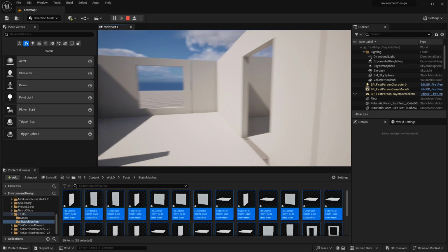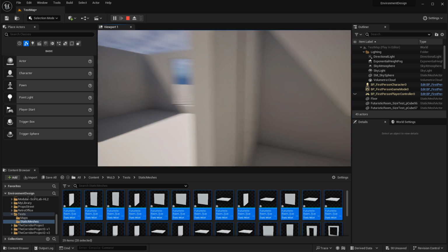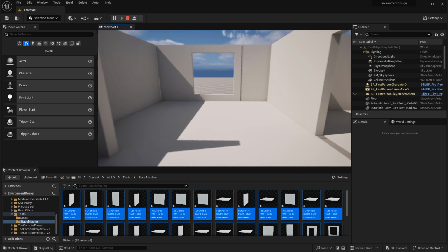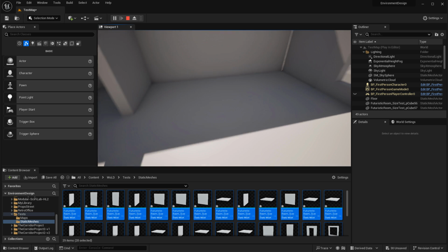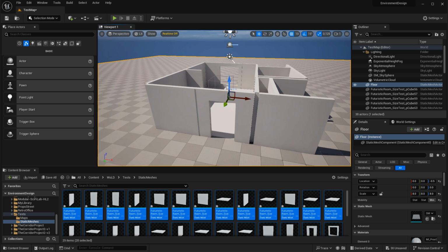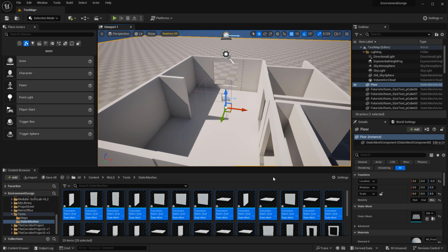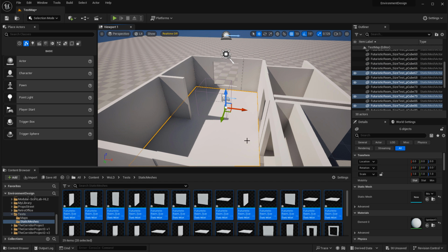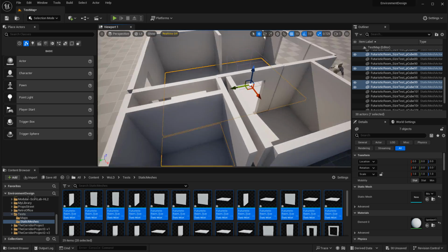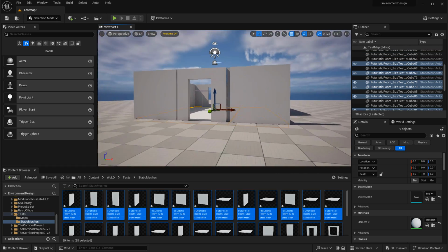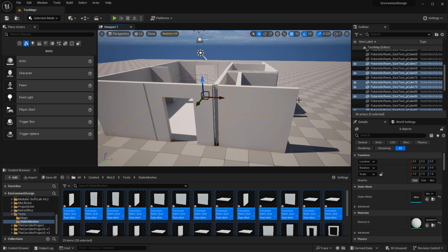And it does. It opens it up a little bit more. Good walkable area. And I'm visualizing what the future possible props may go in here. Will I have space? And it looks like I will. Also, you may want to do a quick test for the ceiling. In this case, I don't want to go back to Maya and have to re-export. What I could do is select these pieces for the floor and just move them up to see how it feels with the ceiling, because once you introduce the ceiling, the space changes.